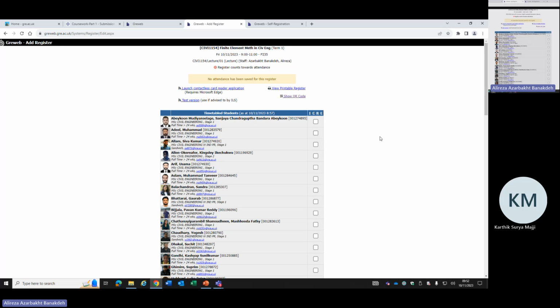It's a support vertical to your plane of work, and it doesn't mean that because it's a support, it will eliminate something in your stiffness matrix. It doesn't. You still have three degrees of freedom here, 1, 2, and 3. And here also the same.